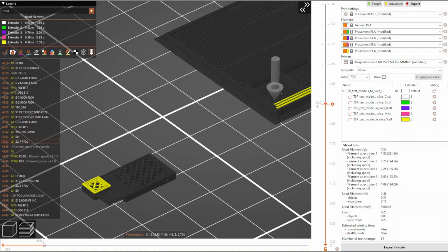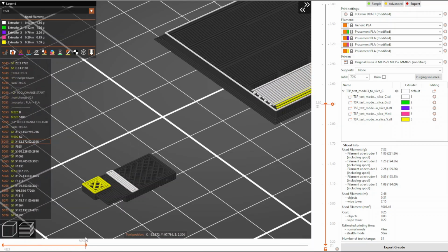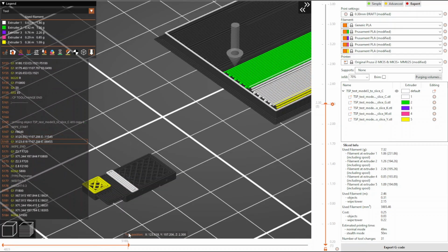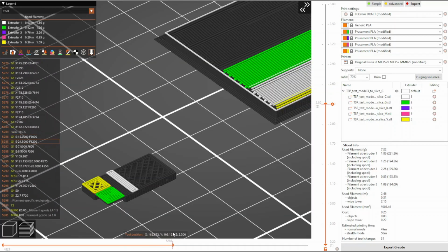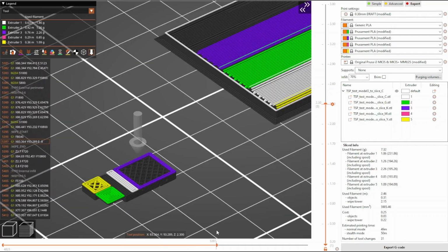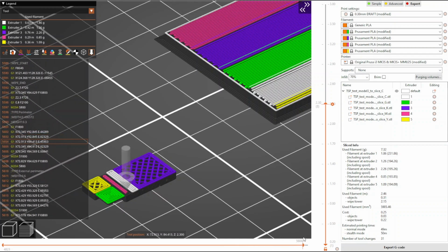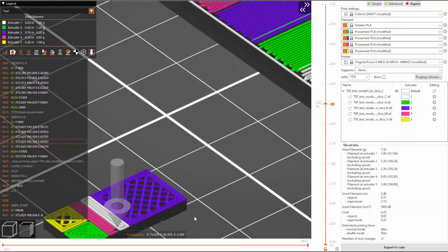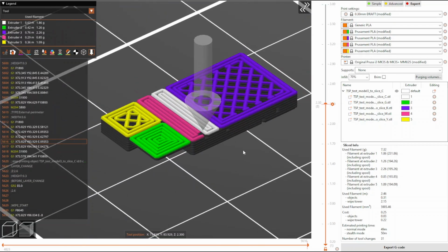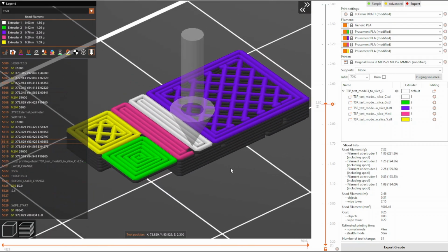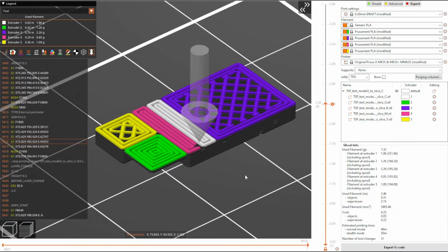For each color transition within a layer, the material is switched, requiring the 3D printer to purge the new material from the same nozzle, and each purging segment takes time and contributes to the wipe tower formation. The layer is partially fabricated, and then, if a new material is required, the purging procedure repeats again. The iterative process continues until the entire part is complete.